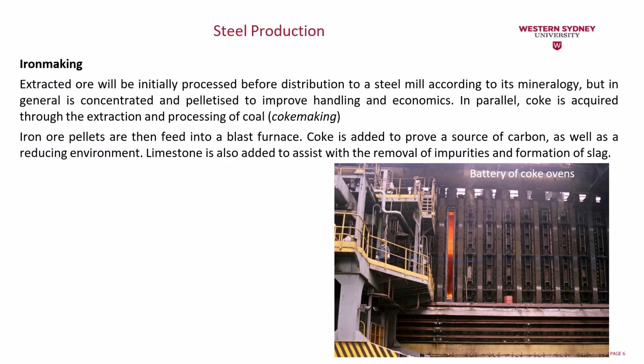Coke is going to be added to improve the source of the carbon as well as the reducing environment. The limestone is also added to assist with the removal of the impurities, forming what we know as the slag.